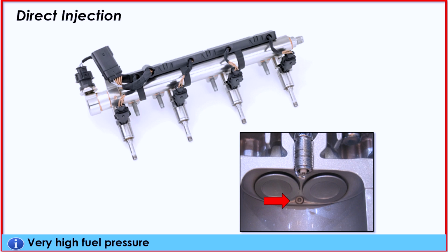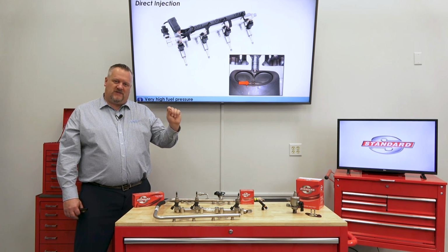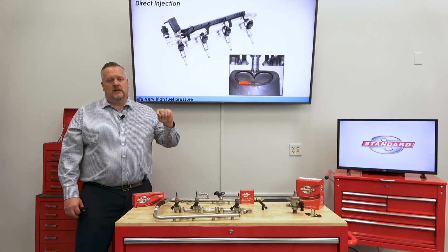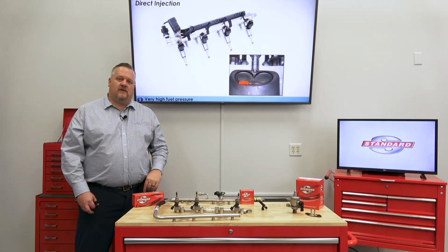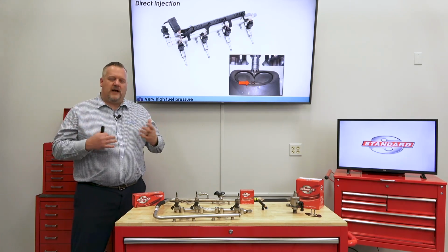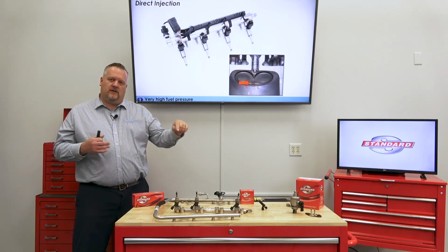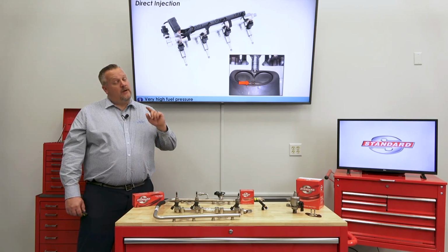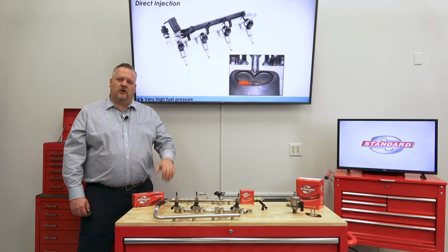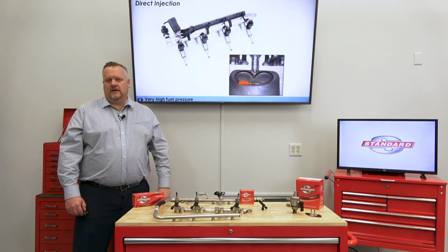And you know what, we're probably still not perfect, but welcome to today's gasoline direct injection systems, where we're seeing these things idle at about 900 psi, and under RPM, we're seeing up to 2200 psi. And these are much more precise, accurate fuel delivery systems, which are directly injecting the fuel into the combustion chamber itself. So we're not waiting for it to mix in the intake or possibly puddle on the intake valve. It's going directly into the system. So much more precise and accurate fuel delivery. But in many cases, there still needs to be some sort of a correction being made to fine-tune the vehicle.